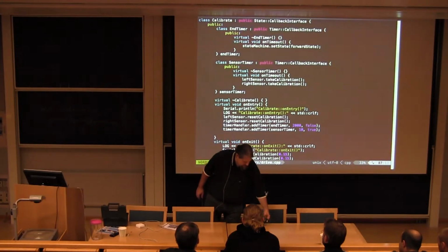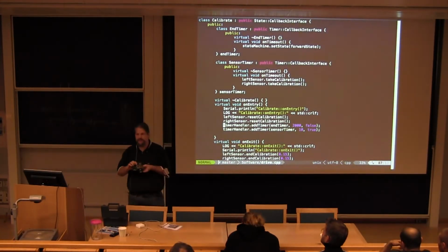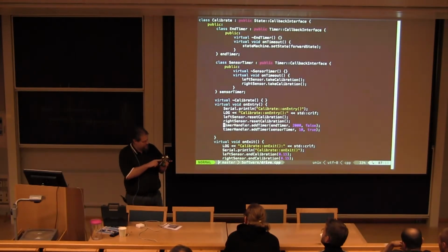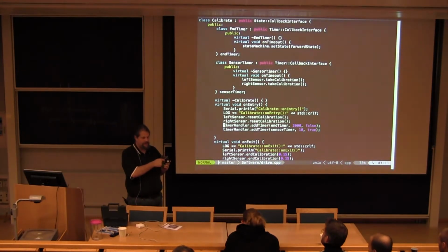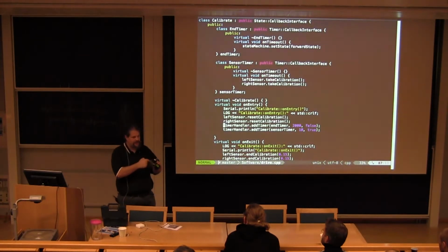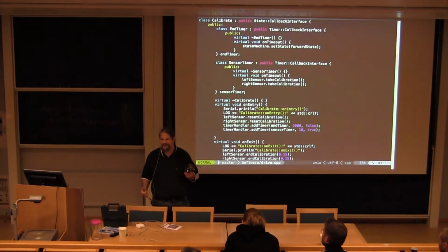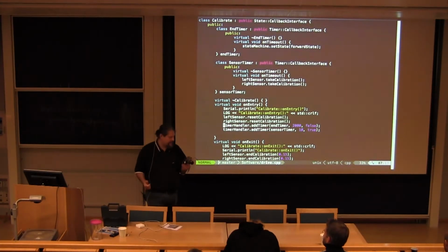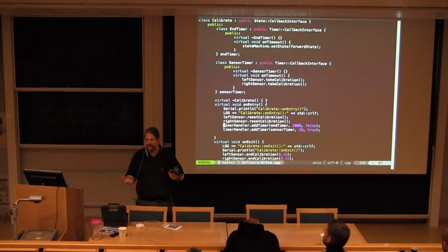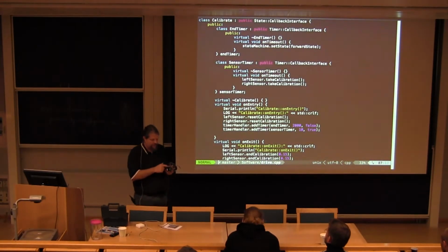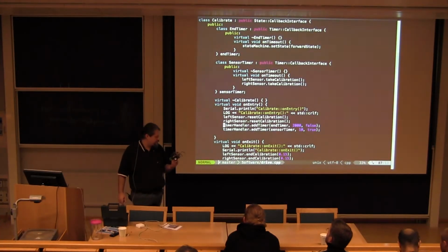And I haven't done that yet because I was using this very simple prototype board where I put everything in. And on the Arduino here, that one is not aligned with the same distance. And so I can't use any of these digital I/O pins. I can only use 8 of them. And I need 6 to run the engines, and the first 2 are the TX and RX connected. I could read, but it still doesn't work enough to get these 4 encoders down here, so I had to make a real board to actually be able to read them.